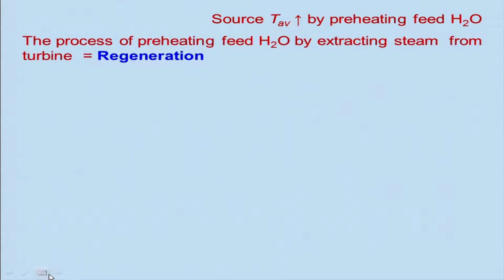Now, will we give the heat externally, or can some of the heat be utilized for heating the feed water? If we give it externally, then we cannot really enhance the thermal efficiency, because the work output will be the same. So, if we can use some of the heat which is getting rejected in the condenser, then do that. Then we call it basically regeneration.